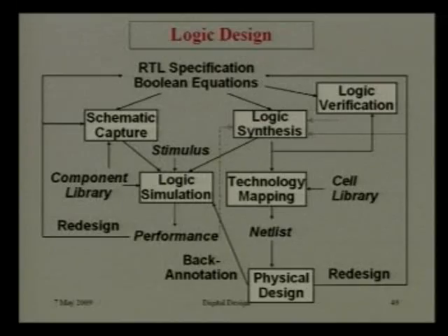And in the library, the size of the transistor, what the delay will be, what area it takes, everything is given with the characteristics of the library. Okay. Accordingly you are choosing, as I told, if you want a delay, you want to use an inverter as the delay block, then obviously you will choose a different type of transistor. And if you want it to act as an inverter, then it will be a different thing.